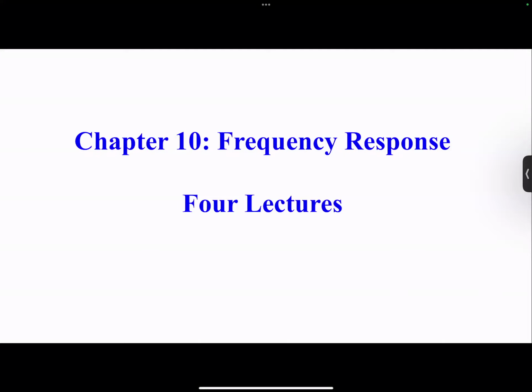Many of them you're able to go in and change the mu, COX, and W and L. So when you change all those parameters, it hopefully will fit your model. If they don't give you the right result, which means either you have a wrong device or you have a wrong model, so you have to change the model.